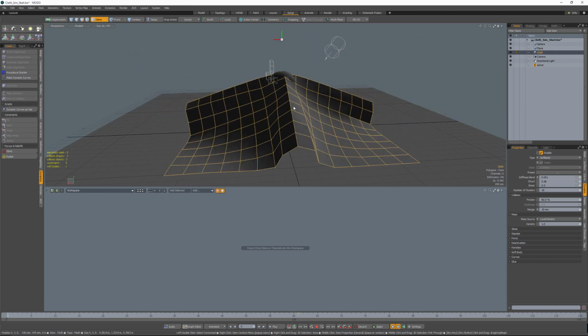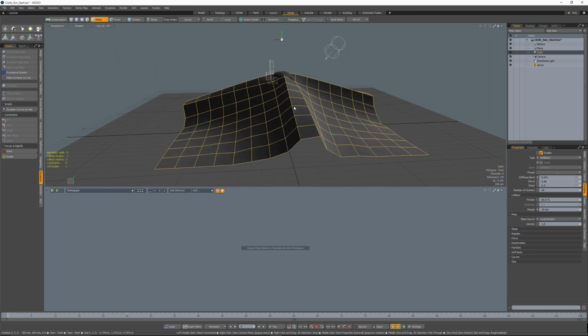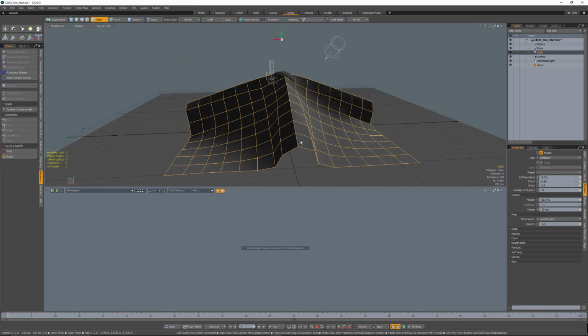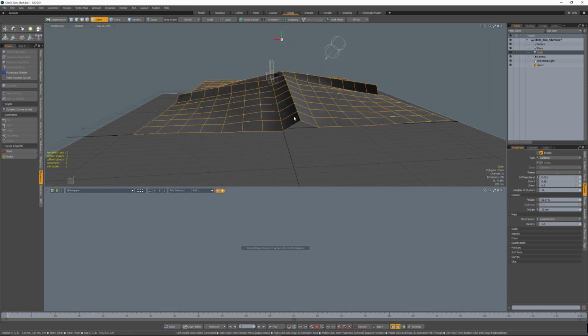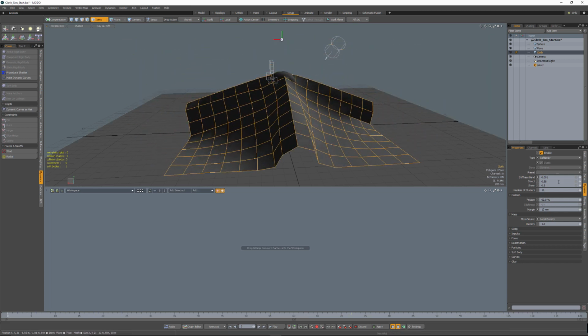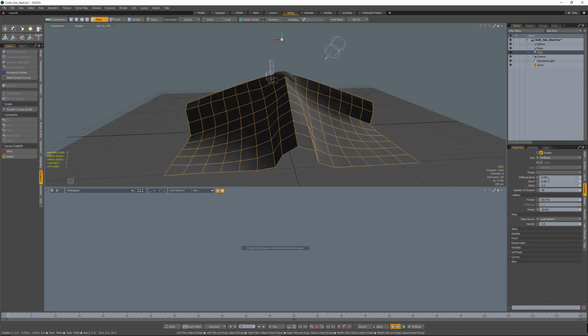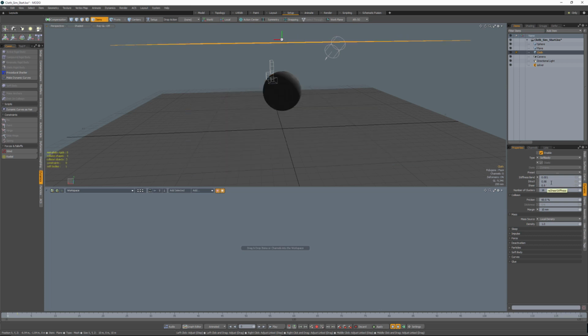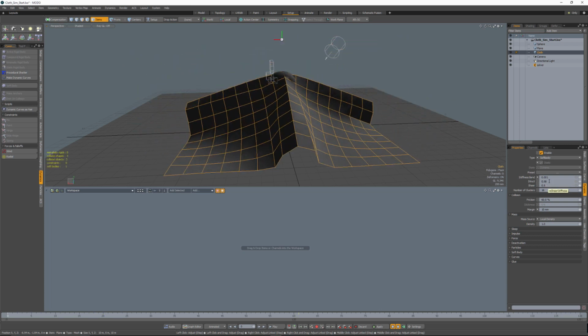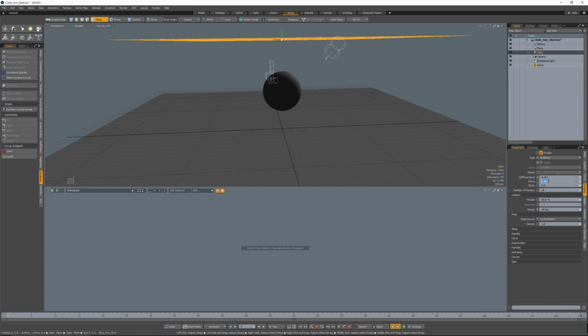What it does is draw an X through the polygon, so you end up with a pyramid or an X kind of shape, and it allows the polygon to bend across those two diagonal edges. It's as if it's making 4 triangles out of each polygon, and those are allowed to give and flex, so you don't end up with completely flat polygons anymore, but those polygons themselves will give. We want this to look fairly soft. I want this to look like cloth, maybe a nice medium thick piece of cloth. So I'm going to decrease both the struct and the shear. Let's take the struct, and I'm going to put it all the way down.